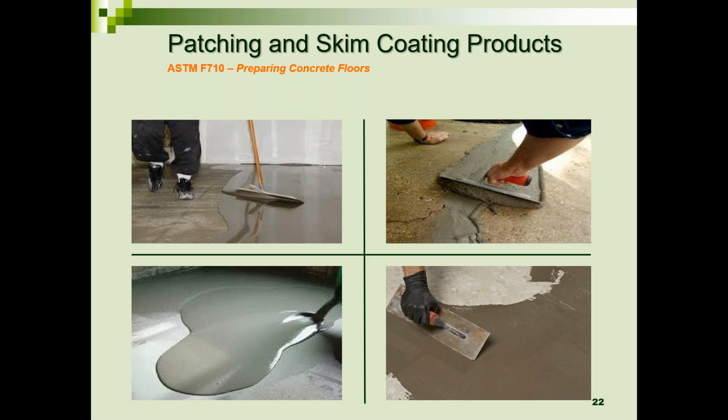Now we're talking about leveling materials to prep a floor prior to tile installation, but you also have patching and skim coating products available to use. These can be used by themselves or in conjunction with leveling materials. The trowel grade patch that we see on the top right, you could be filling in cracks with that, non-moving cracks. You might have an isolated depression or deviation in flatness where you don't need to level the whole floor. You may use a patching compound instead.